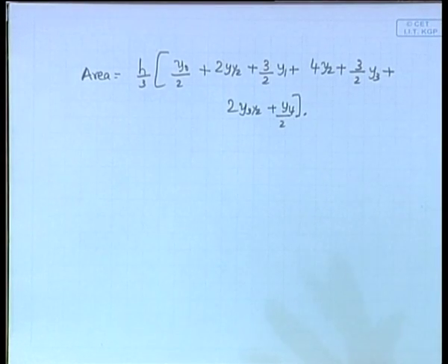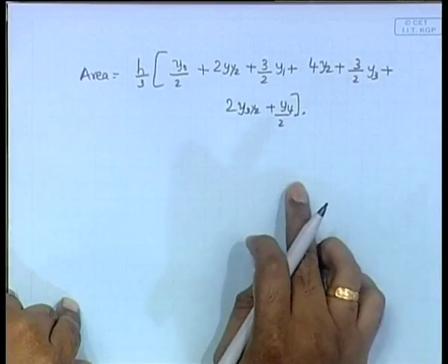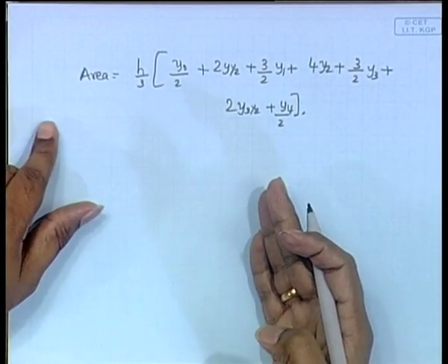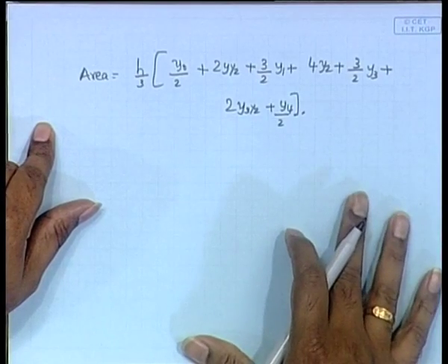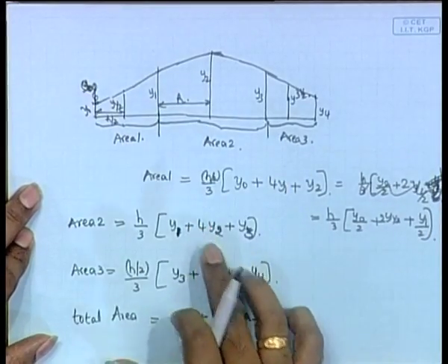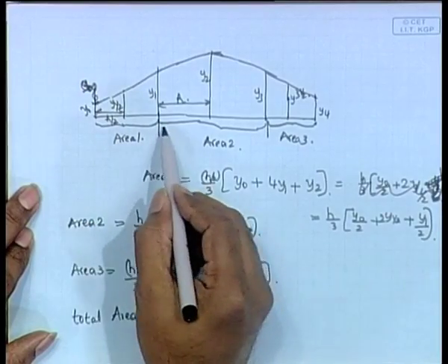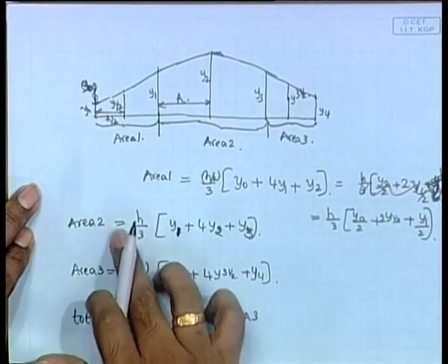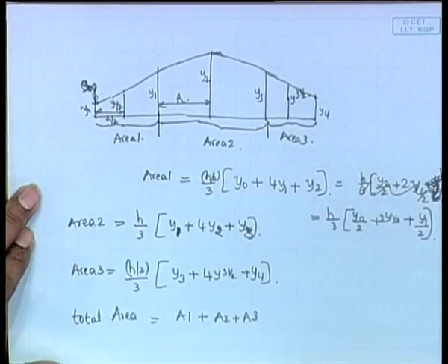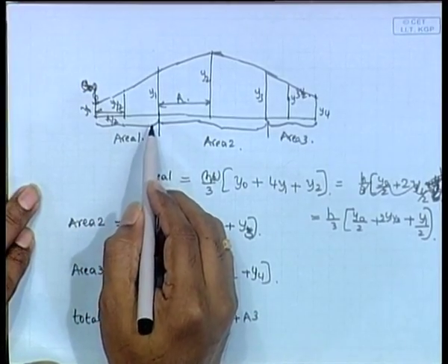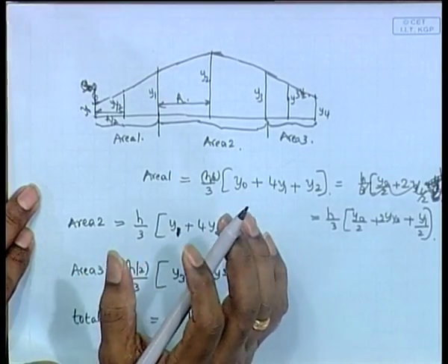So, you cannot really predict your answer in this case. Of course, you can memorize this, but you won't have the same number of ordinates. So, you do not memorize any of this, that is not the goal. Your idea is just to do this summation. The only thing to remember is this is h by 2 and this is h. Other than that, if you have all your y zeros proper, you just sum up. Remember you are doing Simpson's first rule, so always take 3 ordinates and divide it, then you won't make any mistake.